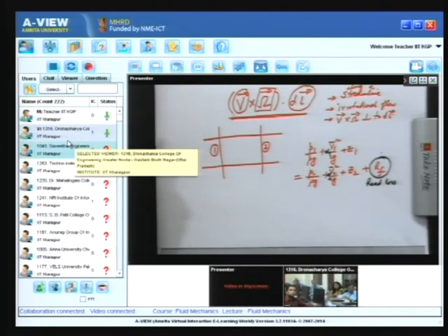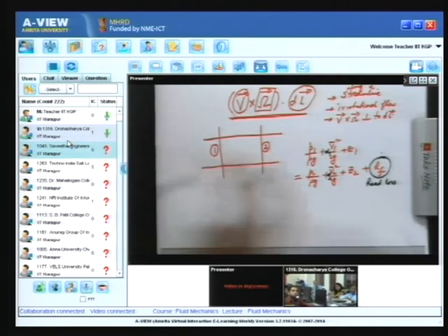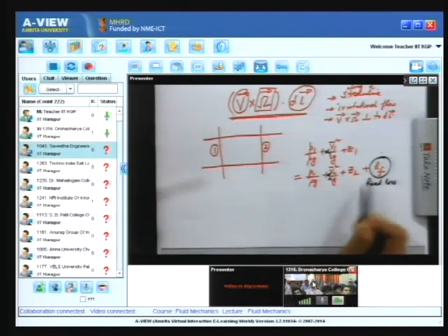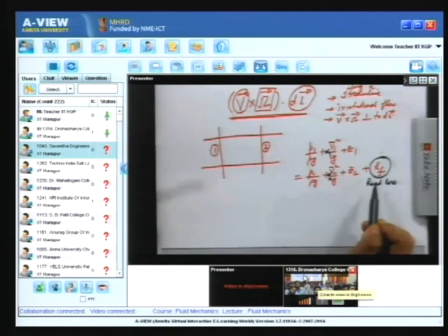Just like if we rub our palms, we see that our palms get heated. So there is a change in internal energy. That irreversible conversion, along with some heat transfer across the pipe, all these effects are accumulated in the form of this head loss.